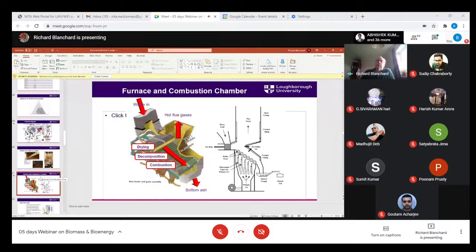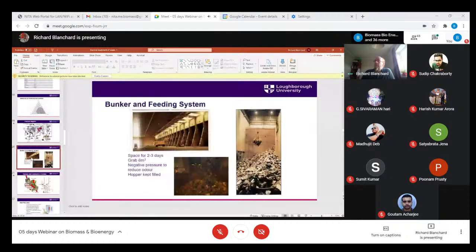But generally plants can operate effectively with whatever goes in. But you can get things going wrong. Gas cylinders, for example, could get inside. If someone put in a propane cylinder inside one of these, that could cause problems. It's not always possible to find these in the waste, because even a small gas cylinder, a 35 litre or a 15 litre one, could get inside and still have gas in it, and would probably explode. Or at least the valve would probably go first, so it wouldn't necessarily explode.